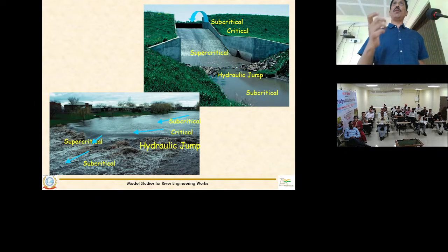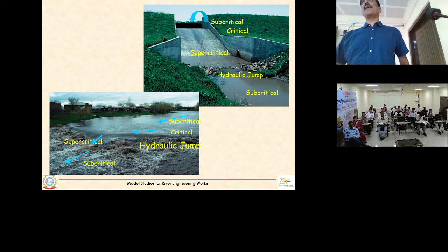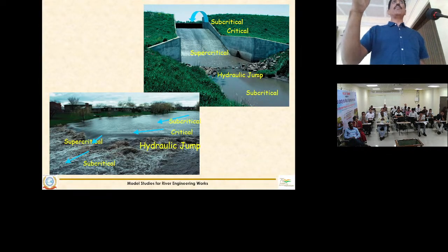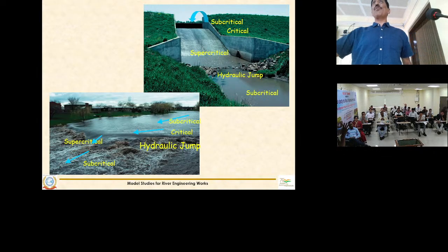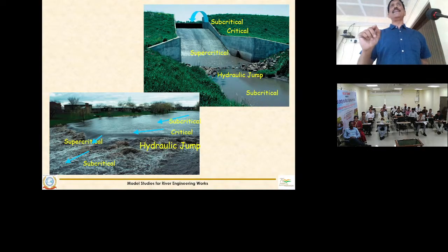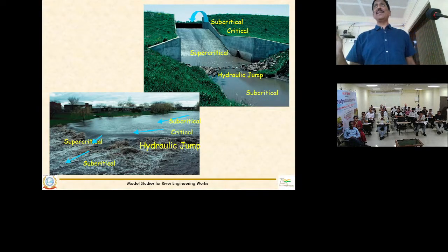If you use the standing wave flume or any other flume, it is based on the concept of the critical depth. So at a certain point, when the flow is passing through the weir, it will pass through that critical depth, and that is the location you should measure, because the rating curve is C_d L H raised to 3/2. C_d is constant, L, the length of the weir, is constant, and the head is changing. So at what portion should you measure that head? That is very critical. It's the critical depth. That head is the critical depth because it does not depend on the flow regime.